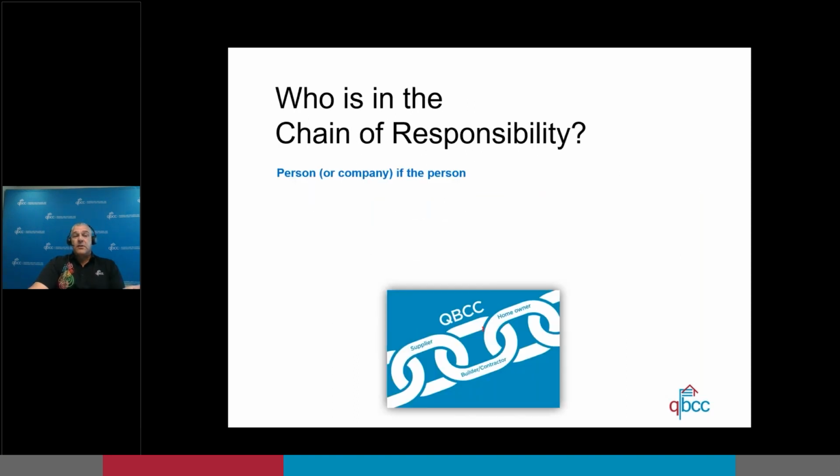Okay, who is in the chain of responsibility? Well, that's simple. That's a person or a company, so the entity. If the person, as it says there, designs, manufactures, imports, and supplies. So who's the designer? That's not you as the architect. That designer would be a person who invents the product. The manufacturer, so if you make a product, you have a responsibility. The one that I see that we will be looking at a lot more in the future is the importers. So if you bring a product in, you have a responsibility to make sure that the product is not a non-conforming building product before you import the product into Australia.